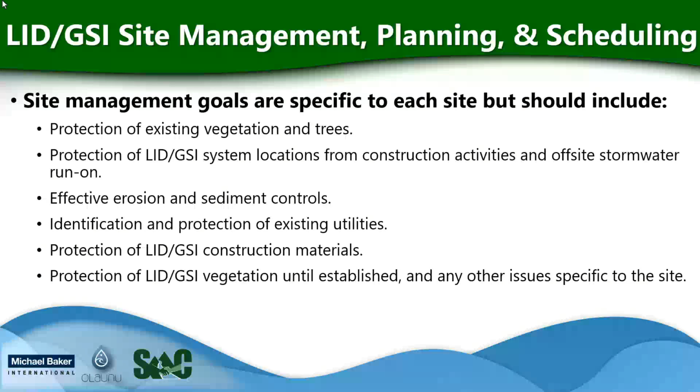Site management goals should be developed specific to each site, but should include protection of existing vegetation and trees, protection of LID and GSI system locations from construction activities and off-site stormwater runoff. This is a critical element to ensuring the future functionality of these systems.